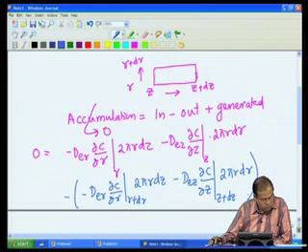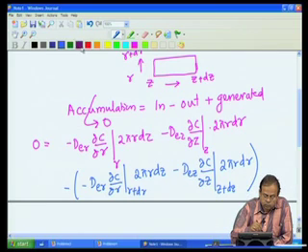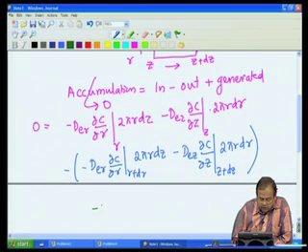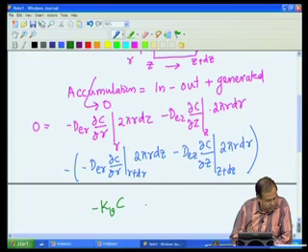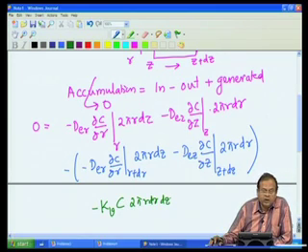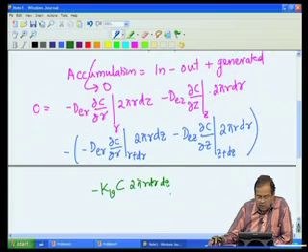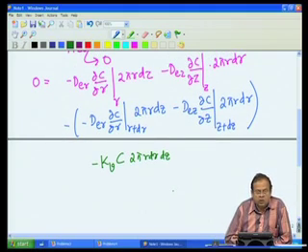So, that is what is going out, and what is being generated? What is being generated is actually this is getting converted. So, that is minus k_V into C, and what is the area for this? The area for this will be 2 pi r dr dz, rather the volume, because the rate is per unit volume and the volume of this small cross sectional element is 2 pi r dr dz. So, this is my general mass balance equation.